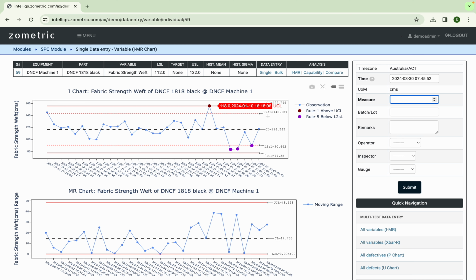As an operator, if I look at these control charts, there are two benefits. First, I remove the guesswork in setting the machines or making adjustments within the machine. I will not take an action unless I see a real instability in the process. Second, I will make the adjustment whenever I see a trend or any sudden deviation in the process, like rule 1 or rule 5, which is a trend. I will take appropriate actions whenever required. By not taking action through guesswork, I am actually reducing the variation and also helping improve the productivity.